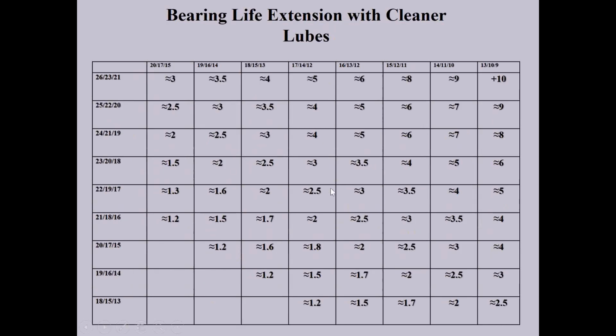So look at bearing life. Bearing life, it says 2.5 to 3 times when we clean up our oils just to these levels. And if we clean them up even farther, look at that, 3.5, 4 times. Now, I've got a couple of my customers that tell me that these charts are not even right. I've got a customer in Chicago that's put automatic lubers on with synthetic oil, and he's getting 6 years out of some bearings that he used to get 8 months out of. He hasn't changed the bearings for 6 years. So a huge difference in what they're doing there with these cleaner lubes.